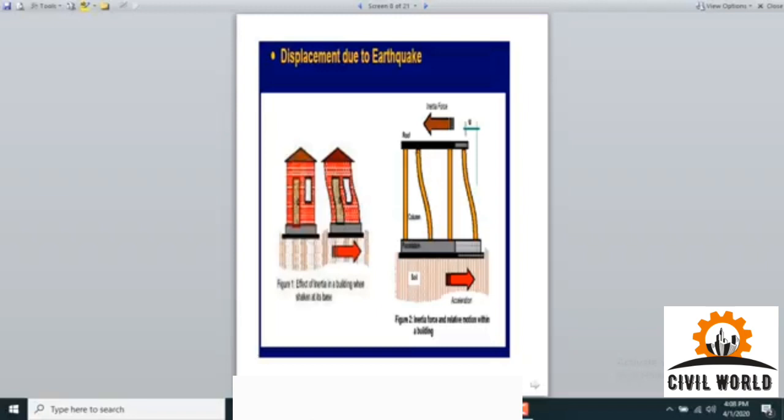This joint, this joint. This is the straight column before the wave is hitting it, and this is the same column, but you can see after the wave has put an impact on it, because of the inertia force, the column is showing deflection or deformation along the central axis. So this joint might fail and this joint might also fail. Same is the case for this column. You can see here there is a drift and there is deflection.